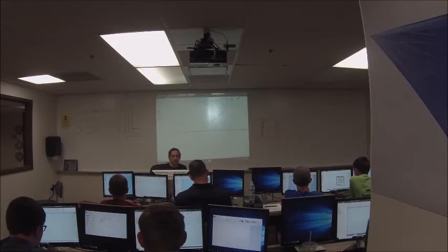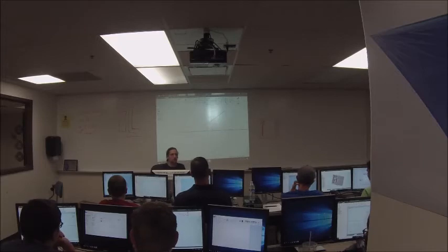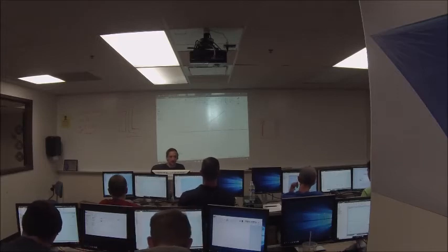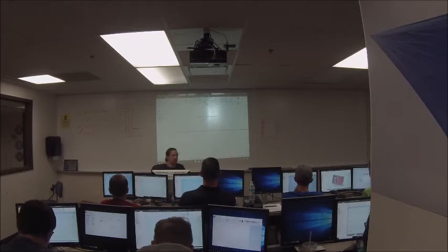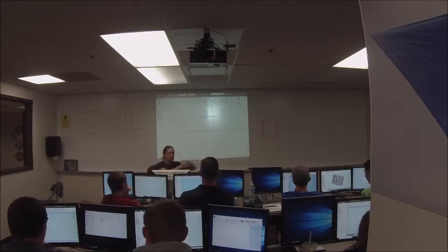This constraint here is a parallel constraint, which makes two lines parallel, obviously. This one's perpendicular, which makes two lines perpendicular. For the horizontal constraint and the vertical constraint, for instance, this line here is at an angle, right? I can click the horizontal constraint and then click on the line, and it makes the line horizontal. And then the line will stay horizontal. No matter what else I do in the sketch, that line's going to stay horizontal.